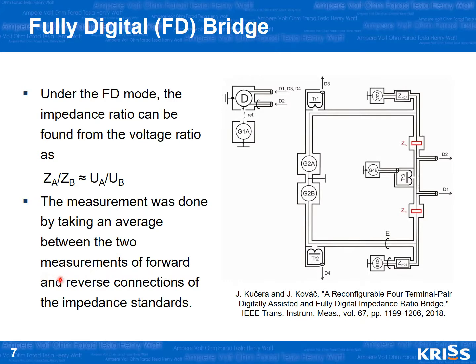The bridge is energized by a polyphase sine wave generator with two output channels. The sine wave generators are synchronized with a 10 MHz reference. The sine wave generator G1A supplies the reference voltage to the null detector of a lock-in amplifier, model Signal Recovery 7280. G2A and B apply the voltages to the impedance standards ZA and ZB as the